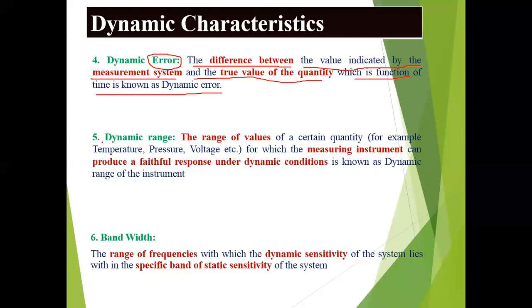Next, coming to dynamic range. The range of values of a certain quantity, for example temperature, pressure, voltage, current, etc., for which the measuring instrument can produce a faithful response. Faithful response is nothing but correct response.